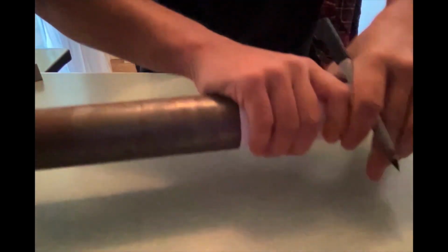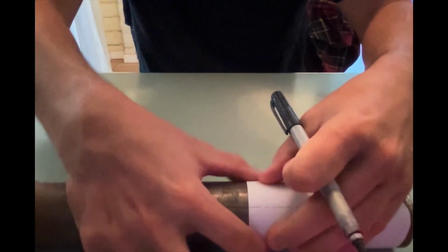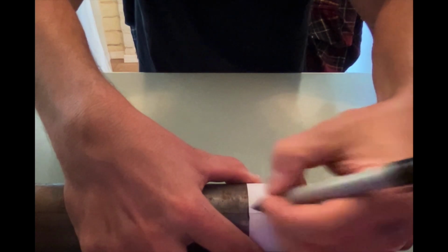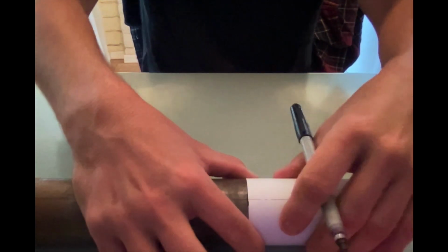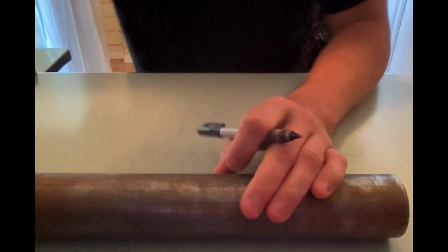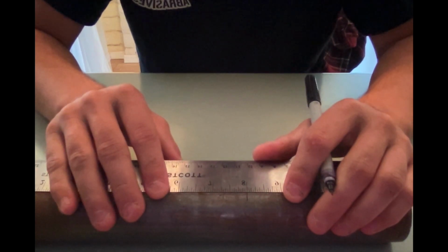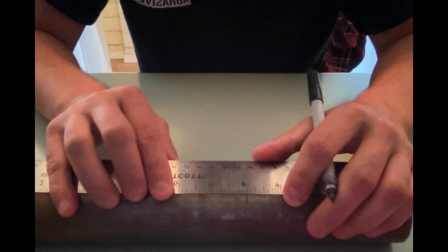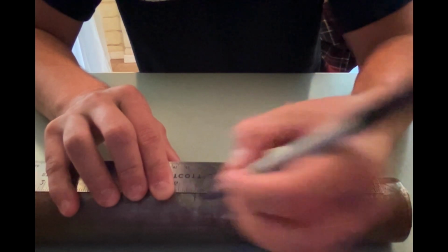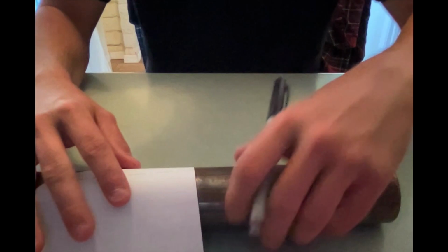Okay, now before you let go of that template, we need to make a little mark at the edge of our inner edge of our template. Just a little mark across our straight line. And then, like I said before, you want to remember that dimension that we had created to separate the templates. So I believe I had that set to 1.5 inches. So we will mark 1.5 inches from that line we just made. And that's going to be the start of our second template.